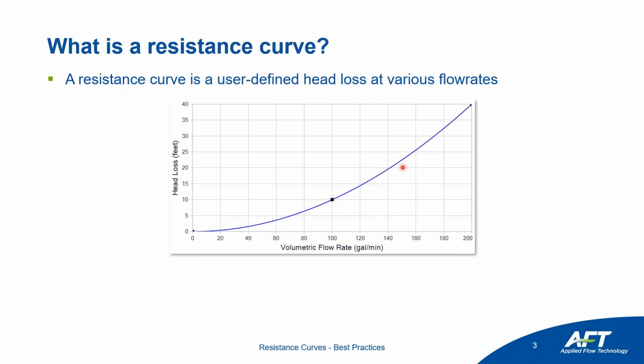We can then curve fit that information, so that way if we're not operating at that same exact flow rate, let's say we're making other changes to the system, replacing a pump, removing scaling on piping, we can see how that flow rate will change and also how the pressure loss through that specific component will change as well.